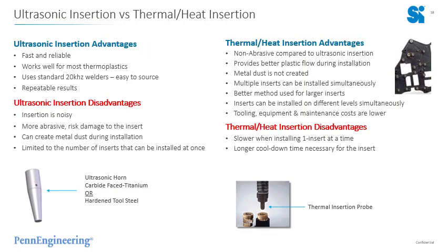Ultrasonic insertion versus thermal heat insertion. A lot of pros and cons to each method. So let's go over the advantages to the ultrasonic insertion. It's fast and reliable. It works well for most thermoplastics. It's easy to source the welders and the welding horns that they use, and you're going to get repeatable results.